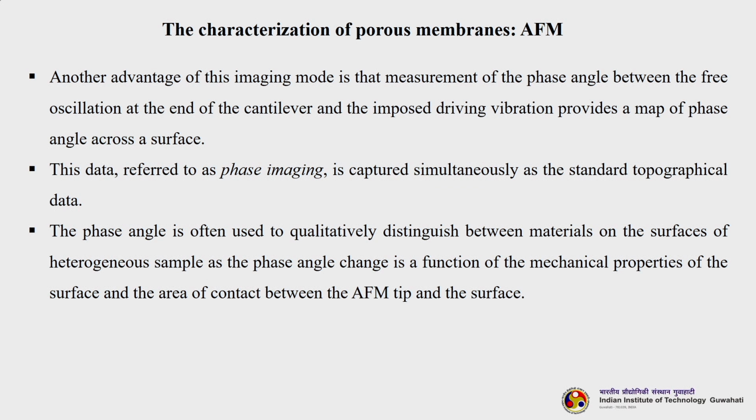An advantage of this imaging mode is that measurement of the phase angle between the free oscillation at the end of the cantilever and the imposed driving vibration provides a map of phase angle across the surface. This is referred to as phase imaging. It is captured simultaneously with the standard topographical data.